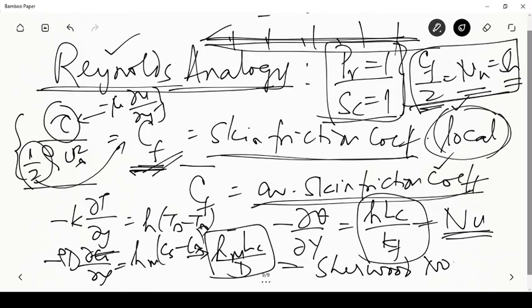similarity or analogy that we normally make use of in understanding these three sciences: fluid mechanics, convection heat transfer and convection mass transfer, and similarly conduction heat transfer, conduction mass transfer and viscosity. These terms are these equations and therefore their solutions are very similar to each other, and therefore the analogy between them can be used, particularly when the Prandtl number and Schmidt number are equal to unity.